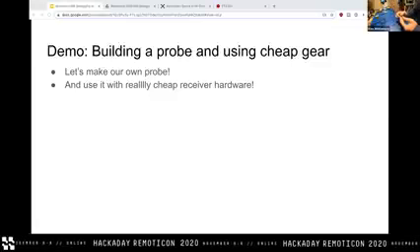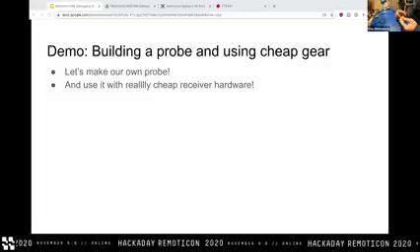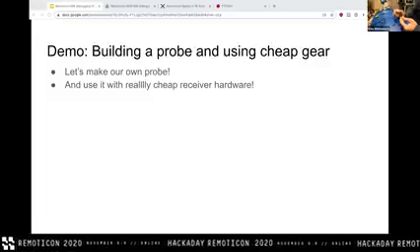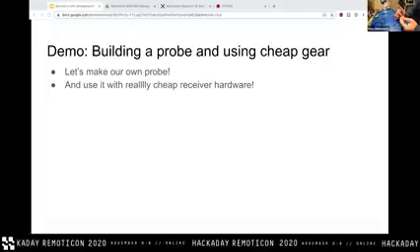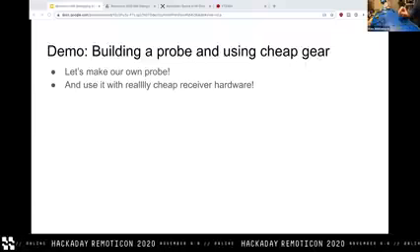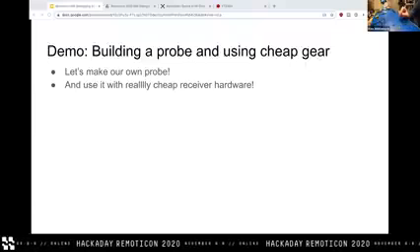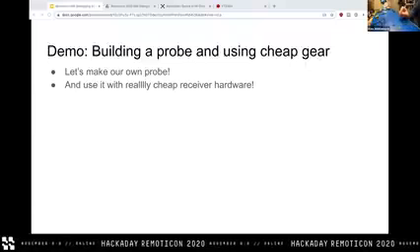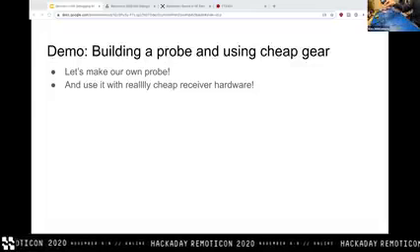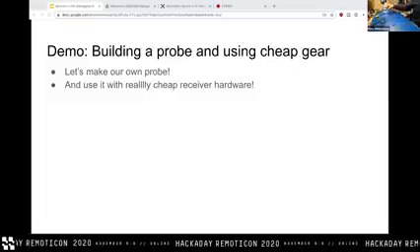So, you know, this will have terrible rejection in an RF sense, but also terrible sensitivity to electric fields. So we're basically just relying on the terrible sensitivity to E fields of a probe that just has a short circuit to ground effectively, and measuring primarily magnetic field instead.